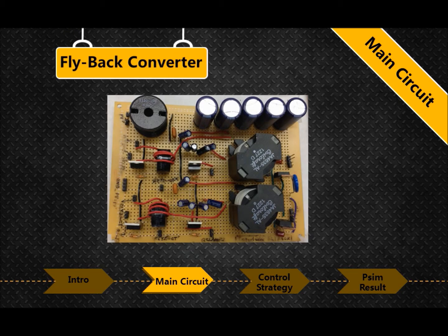Next come the flyback converters. Here is our board of the flyback, a pair of flyback converters. They're called interleaved flyback converters because they are actually phase reversed. This topology is used basically to reduce the ripples and to increase the power factor.